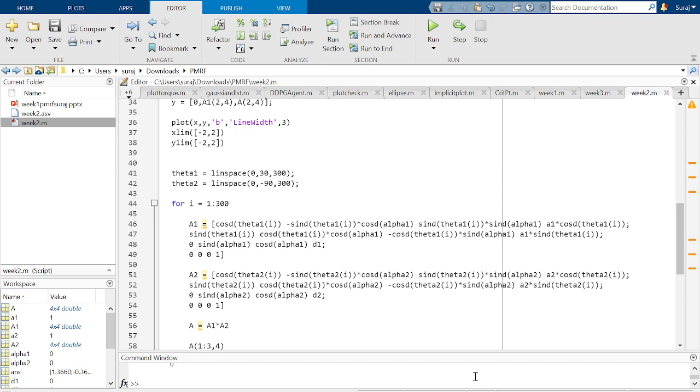You know the coordinates of the circle on the wall, you applied inverse kinematics and found the joint angles of the robot. If you are on a real robot, you just give the joint angles to the real robot and the robot will move in that direction, and you will get the circle on the wall.